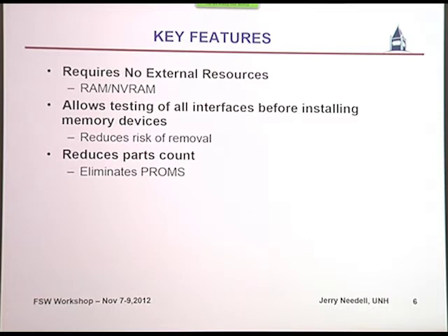One of the side effects of this, as well as giving us a robust platform for fault handling, is that it also gives us a nice test environment, because we can test our board, our CDPU board, before we put any of these devices on it. We don't need any RAM or any SRAM or any CRAM, any NVRAM to be able to bring up the board and check out all the interfaces. And I'll show you that in a minute.